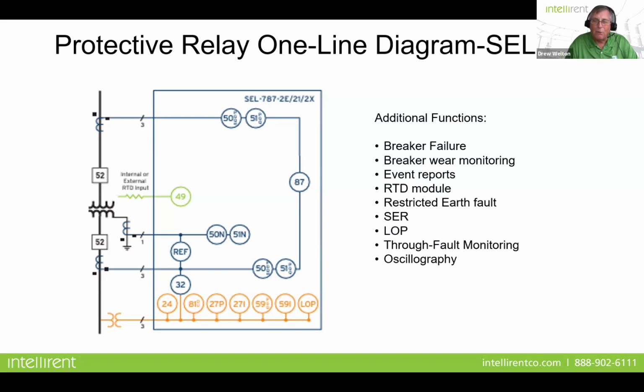So very, very important. The first thing at hand is to make sure that all these functions get utilized, because each of those components not only can give you some valuable information over the course of time, like a through fault monitor, but also in the event that you do have a problem, you can easily diagnose that, yeah, you had a bad trip, and there's potential damage inside the transformer.